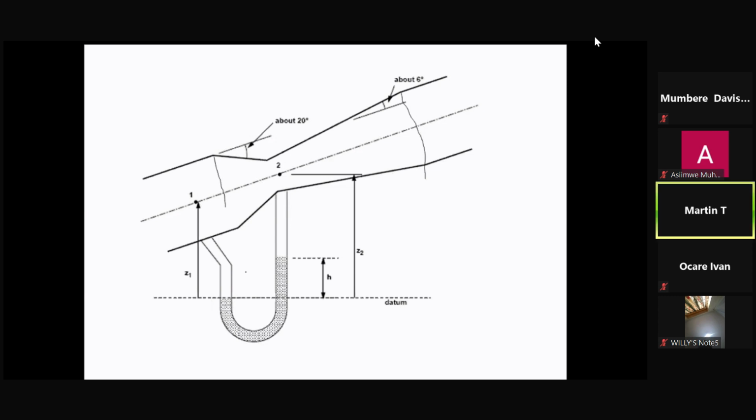If in the second term velocity increases, to stay with the same constant, pressure should drop to compensate for the increasing velocity. That is from Bernoulli's principle. Is it clear now? So when the cross-section area reduces, the velocity increases, and when the velocity increases, there is a pressure drop.